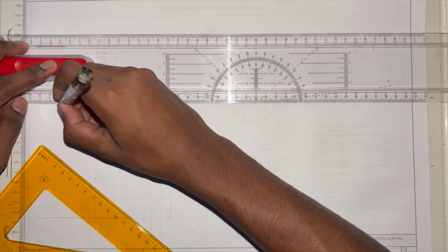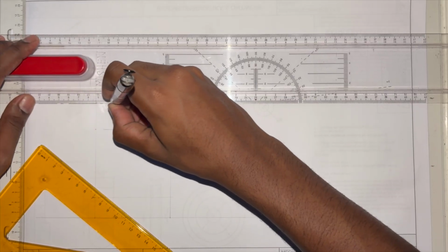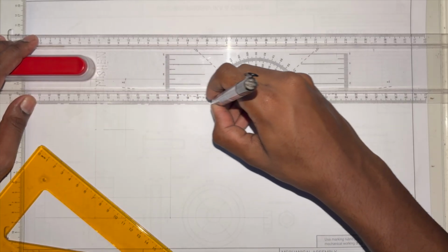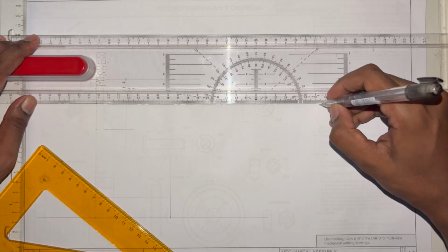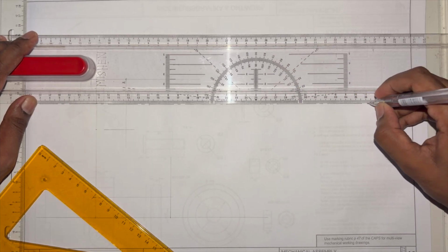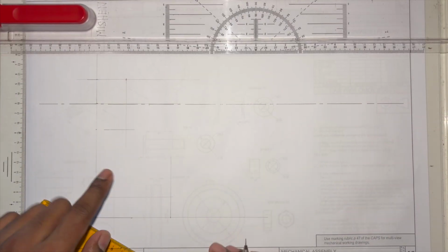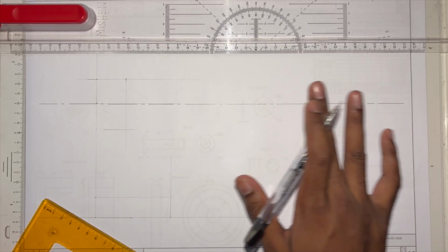is a center line. Now I did mention this in a previous video. I said that when you're drawing a center line for the first time, don't draw it lightly. Don't draw it as a construction line. Draw it as a center line from the go, just like that. Draw it like this at the start, because you don't have to erase it. You don't have to touch it after that. Once it's done and it's correct, that's it, done.